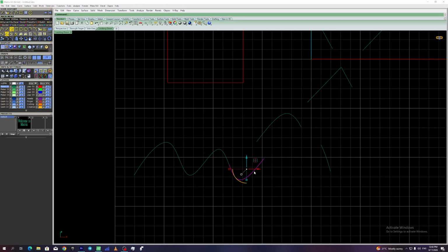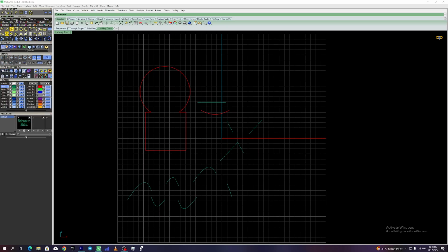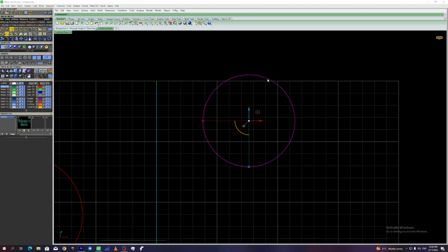There's no limit. However, there's one rule to keep in mind. If you want to split a closed shape like a circle, you need to split it at least at 2 points. Why? Because if you only split it at 1 point, the circle stays intact. Nothing changes. So always remember, closed shapes need at least 2 split points to be divided properly.